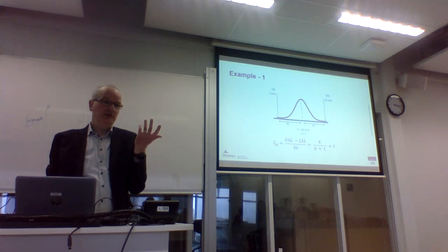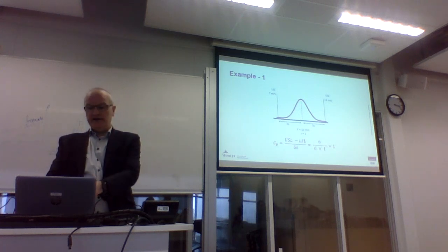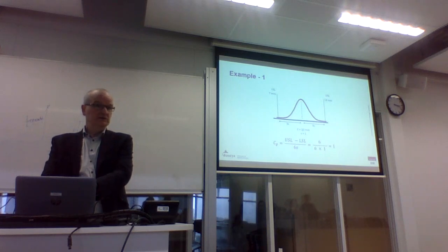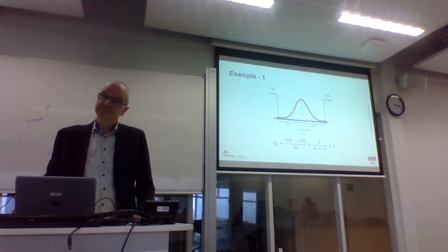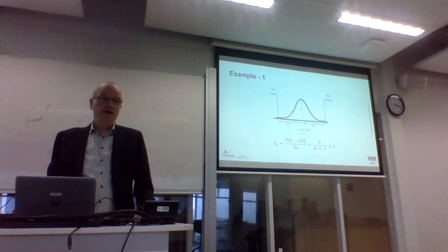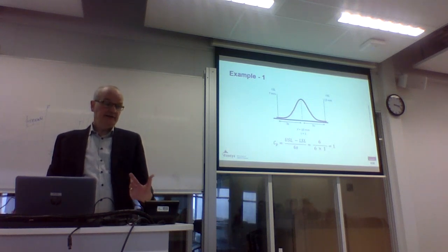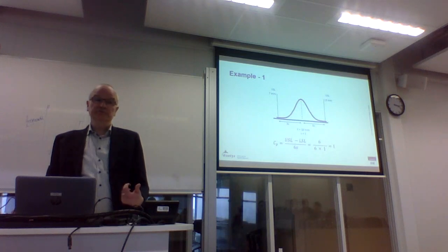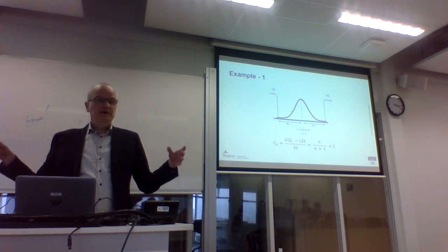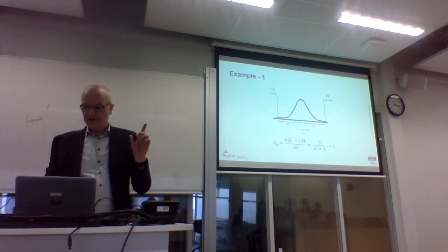I have a pretty capable process in this case, right? It covers as long as I keep my process in control. Most of the products that I produce, by far, are going to be within the specifications. So CP larger than 1 is really without any risk. The larger CP gets, the better you score, right? The lower CP gets, the less perfect you score, because you're going to have a lot of products that are outside of specification. So I'll show you a different example.